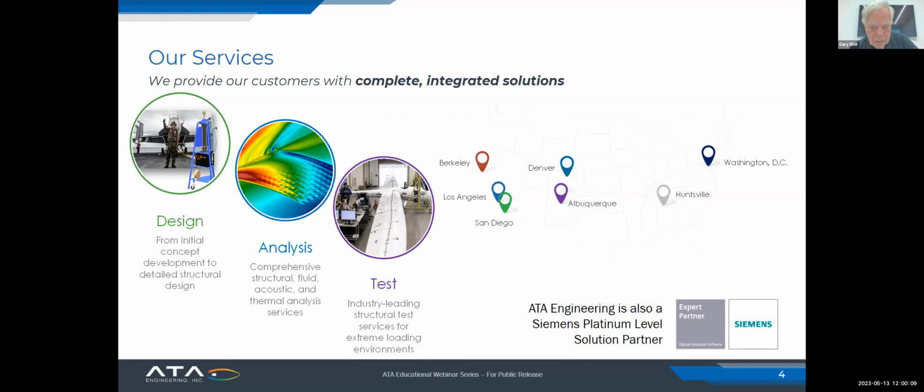You make it as thin and light as you can, within the strength and performance requirements. Then you find out what you've got as a flutter characteristic, and subsequently modify things if necessary. But no, you can't guess these things. The FEM is what gets you the answer.